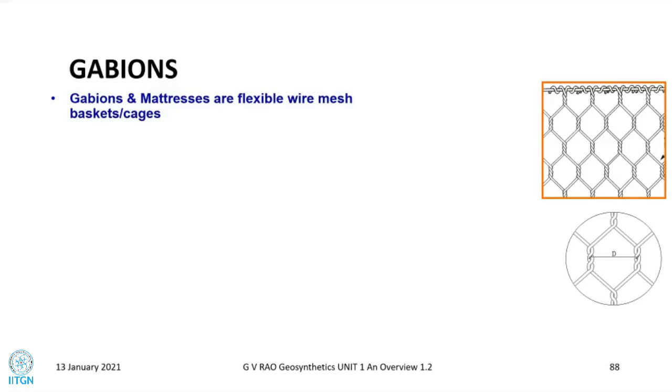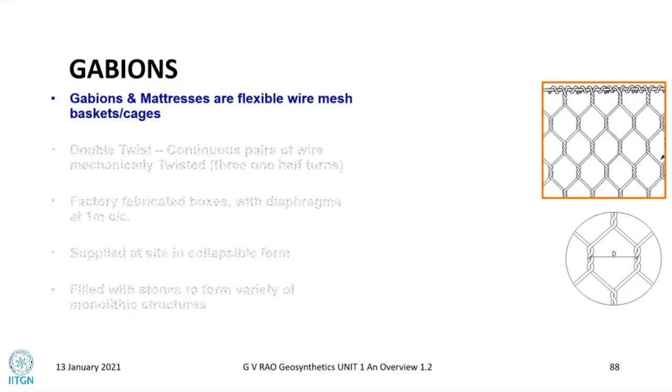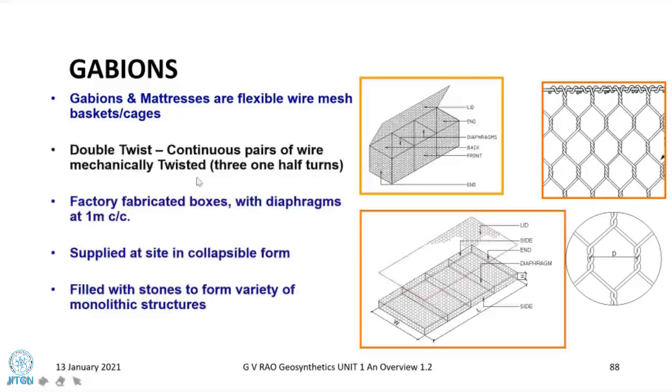Then another equally challenging material, which is becoming more and more multi-purpose, is gabions. Gabions are also called mesh boxes, and they are made of GI wire. The boxes are sometimes made of hand-woven meshes, but these are machine made, which is called double twisted material. You can see this twisting more clearly here, double twisted. In fact, there are round turns for every kind of thing.